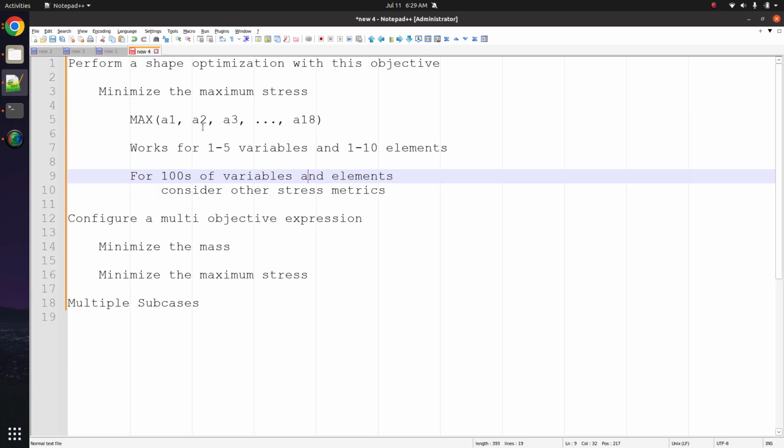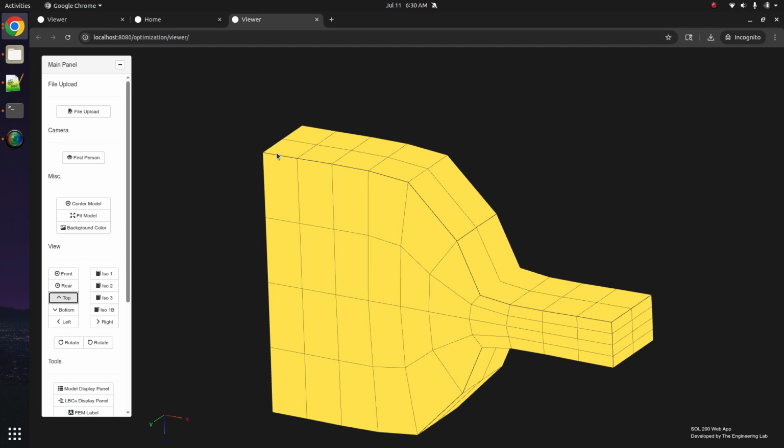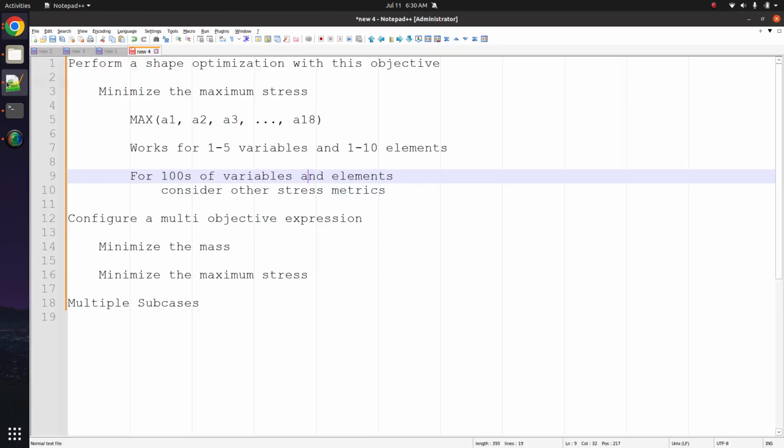We were tasked with fixing that shape optimization. Again, the issue was that the original shapes did not allow for adding material at the region of high stress. So here what we did is we adjusted the shapes. We now add more material here. We reduce the maximum stress.